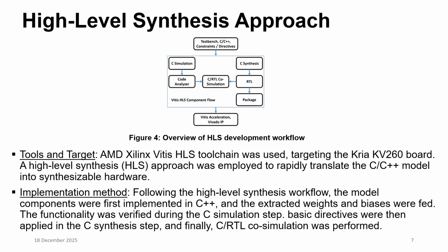We do the C simulation first to make sure the functionality is correct. Then we synthesize the C code into RTL code. Then we do the C/RTL co-simulation to make sure that our software implementation matches the generated hardware. At this point, it is ready to be exported as a Vivado IP, which is to be implemented on the specified board. In this work, we chose the KV260 board.